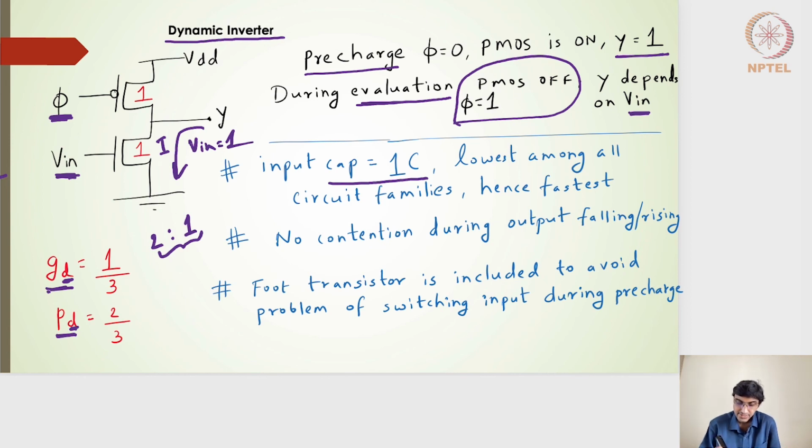Similarly, for the parasitics, the benchmark inverter is again 2:1. At the output side here, I'll see a total capacitance of 1 and 1, so there is a capacitance of 2C here. And the benchmark inverter gives a capacitance of 3. So the parasitic will be 2/3 for the going down signal, right? There are no values defined for the going up signal, so no values are stated for the logical effort and the parasitics for going up.